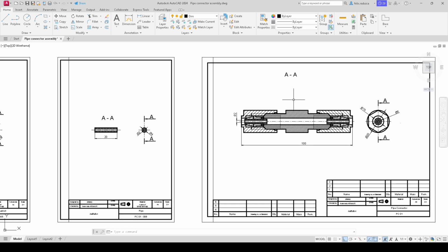So now we can point to different parts here and say which one is part 1 and part 2 by using the mtext command and giving it an initial starting point here and an h value of 7.